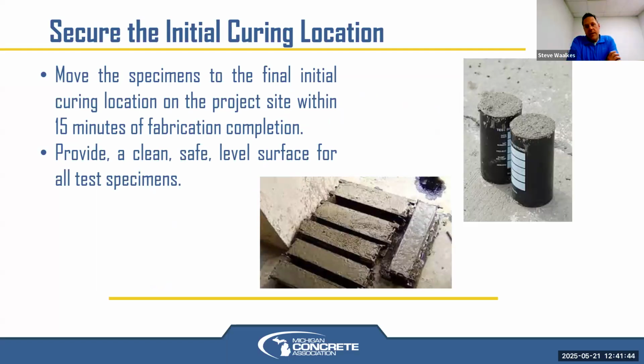Cylinders and beams are very susceptible to that initial curing. Once the concrete's in them, consolidated and struck off, and a cap is put on, or a curing compound has been sprayed on the beams, or a cap on the cylinder molds, they're not brought back to the lab right away.